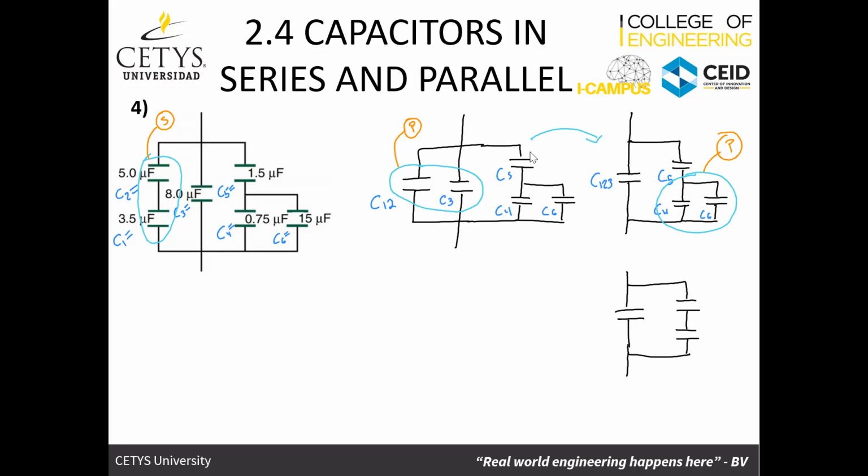Is the parallel to C4, C4? C4 has a junction going up. You can either go up to C5 or right to C6. And the key here that they are parallel is that both terminals are joined with both terminals. C4 is not taking C5. No, it doesn't matter in that case.